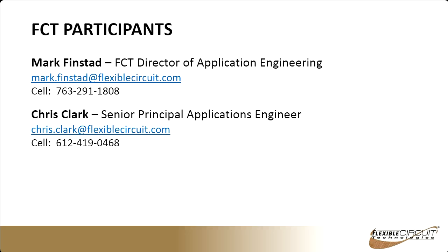Another question on the mil-aero industry. As far as stack-ups, your best guide there is probably the IPC specifications, both 2223, the flexible circuit design specification, and IPC 6013, the performance specification. While these are basically heaters, they're also flexible circuits. It's just flexible circuits that have resistive elements in them. So all of the same requirements will cross over. That's probably your best resource during your design: if it works for a flex circuit, it'll probably work for a flex heater.